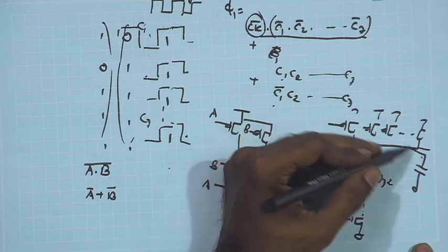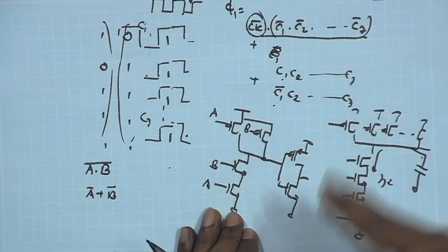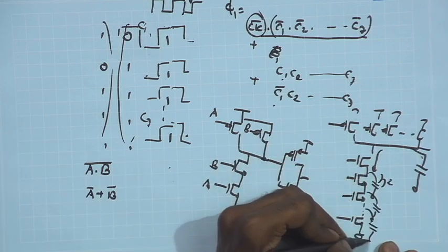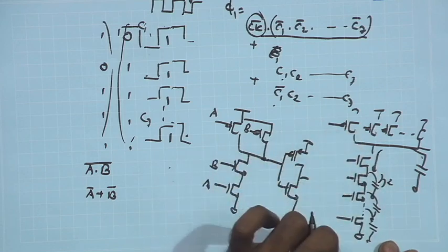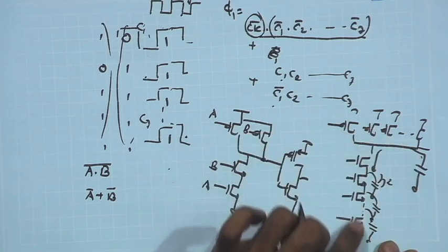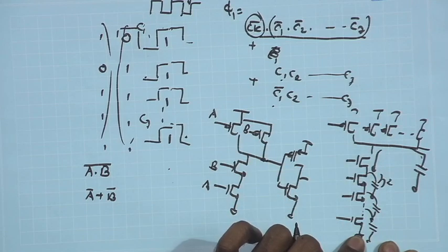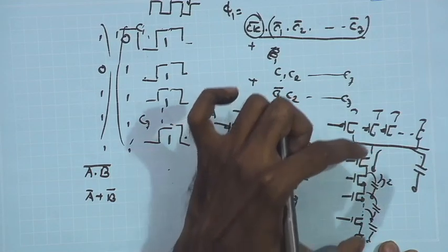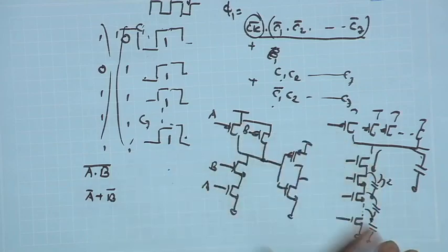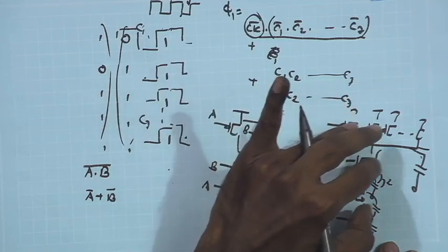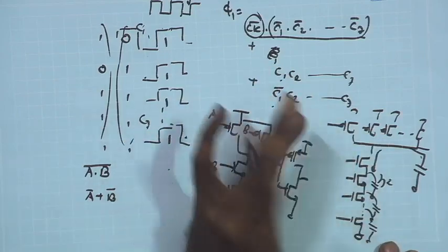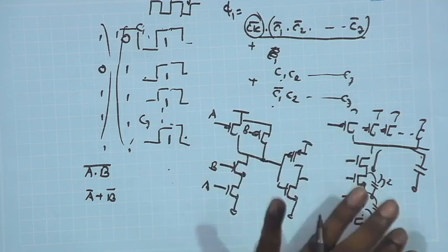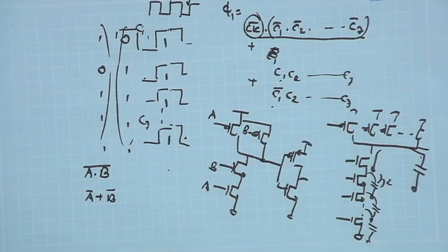If you have n such transistors, the overall transition delay of this logic increases as n square, because effectively you have parasitic capacitances at each point, which increase with n total capacitance charged in the worst case, and you also have the total R in the series connection, which also increases with n. Therefore, the total delay can be shown to be proportional to n square. So, if you stack more and more transistors to implement such logic, it can increase the delay steeply. Therefore, generally people do not go beyond 4 inputs. The maximum number of inputs you can see in standard cell libraries is 4, and better is maybe 3 inputs. Beyond 4 inputs it can degrade the delay pretty significantly.